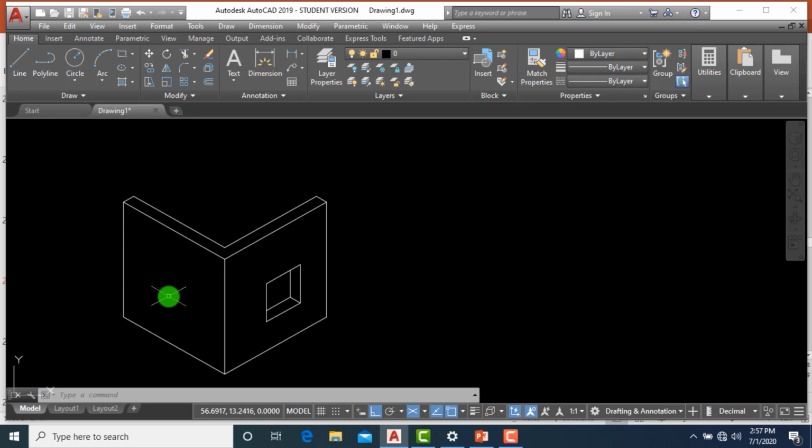Now the other thing is that if you want to create circles, circles in isometric view are basically seen as an ellipse. The moment you have the isometric snap on, I've not taught you ellipse yet, but you can take the ellipse tool, and here the isocircle option is there. So you don't use a regular circle, you use an isocircle in the ellipse tool.